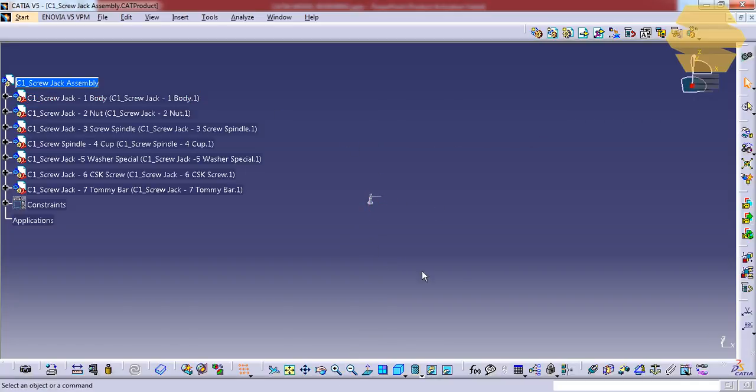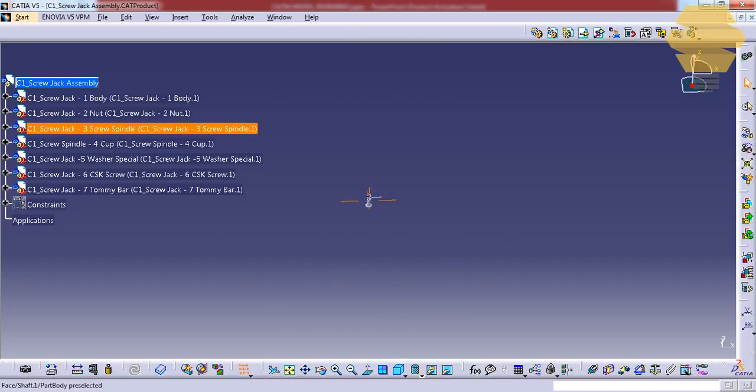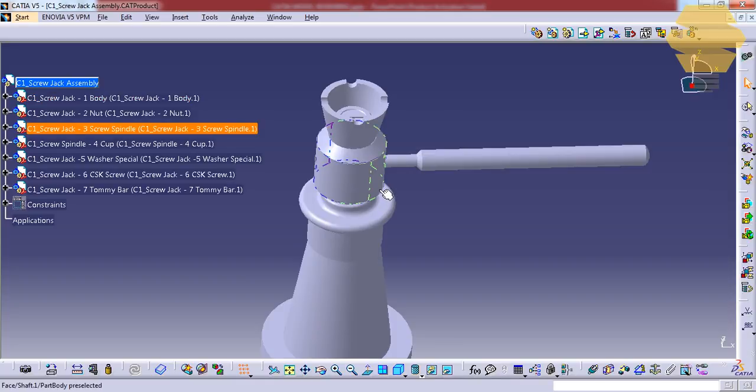Let's say that we have a big structure and this is just a small part of it. What we do is use the shift key and draw a circle using the middle mouse button. You can see, not a circle, like a rectangle, and once you're done, just leave. So it just zooms into that particular rectangle that we have created. So shift and middle mouse button, move so that a rectangle is created, and leave so that it just zooms inside.